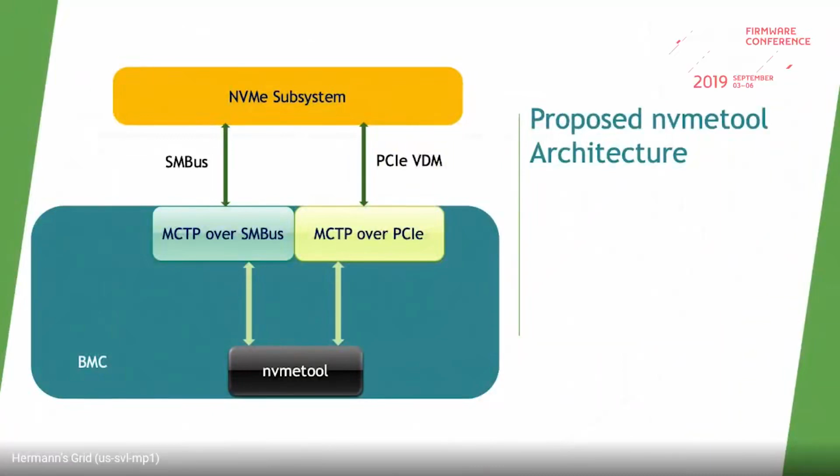So this is something on the cards, the NVMe tool. NVMe is a register level interface for PCIe-based SSDs. These NVMe SSDs will have an NVMe subsystem where there are management endpoints within the subsystem, which can be queried from the NVMe tool. There are two physical mediums, the SMBus and the PCIe, and the NVMe tool should be able to speak to the subsystem using either of these physical mediums.